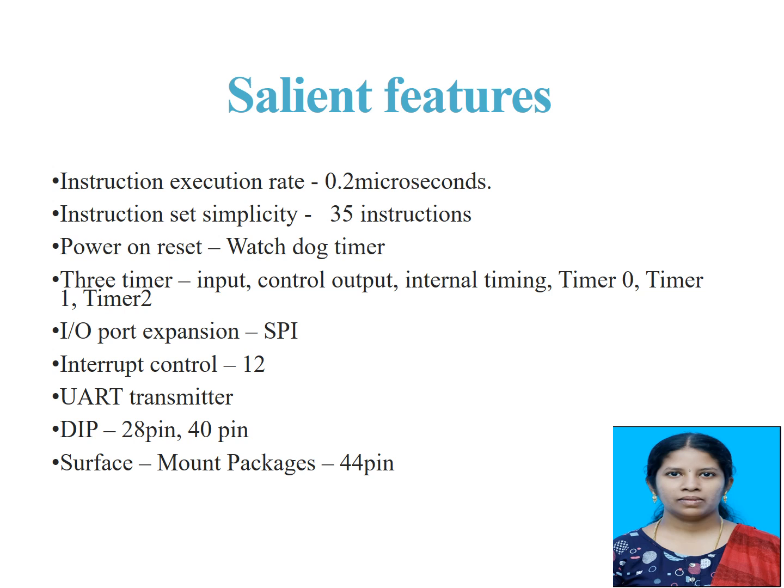It also has another important feature of power and reset, which can be implemented by watchdog timer. It is sometimes referred to as WDT. The watchdog timer is a safety feature that automatically resets the device if the software fails to clear the timer before the predefined timeout period. This watchdog timer prevents a microcontroller from getting stuck in a problematic state and ensures the system can recover from errors. It also has three timers: timer 0, timer 1 and timer 2.